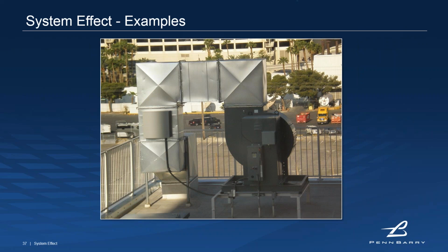One type of transition that's often supplied with fans is like an outlet evase. Not particularly common on commercial fans because we're not running them at the outlet velocities where they're required. But in an industrial application, you may have an instance where you're running at the 5,000, 6,000, 7,000 feet per minute range on outlet velocity, which is very high.